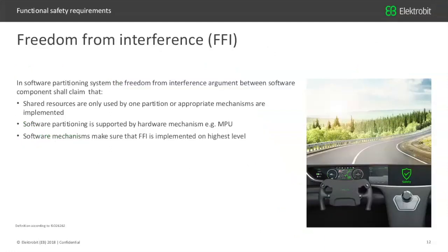Okay, so that brings us to the term freedom from interference. We'll look later on at how I get to the argument for freedom from interference, but here I want to introduce it. It is a method where I can separate my safety functionality from the environment, to make sure that there's no interference between a non-safety part and something which controls the safety system or a monitor.